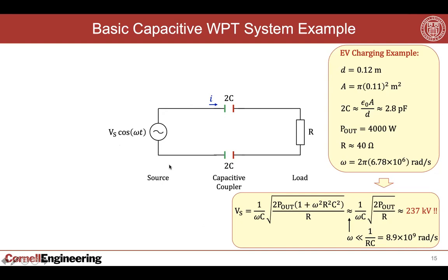And to do that, you would need switches that can switch that fast. And if you look at the kind of switching losses that you would have, a quick calculation will show you, if you looked at even the best quality devices out there, that you'd be losing kilowatt scale of power in those switches. And so it would just not be feasible to operate in the high gigahertz regime with such high voltages, because just the output capacitance related losses in those transistors would basically destroy those transistors. And so really you have to look for another solution.